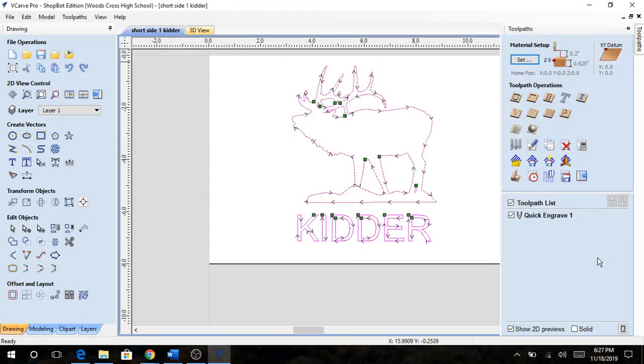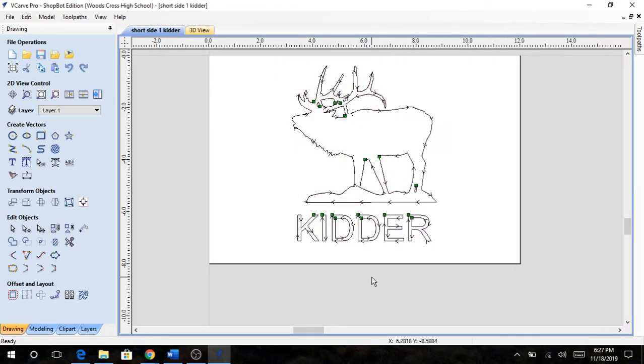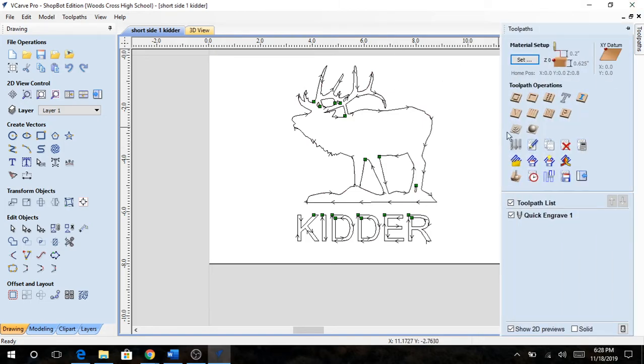It's really important that you save it in those two different spots. File Save is saving the drawing and our toolpath. Going to Toolpath and saving the toolpath is what we're going to take. That's the G code. That's what we're going to take out to the router and plug it into the computer and run it. Okay? Got to save both of them in those two spots.